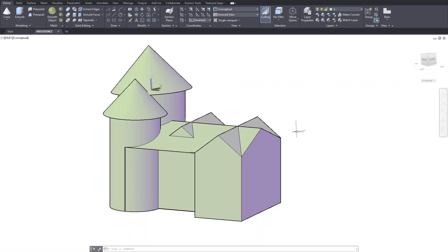And then you need a land, obviously, okay? You have to have some kind of land at least, some kind of ground, and the windows. So we're gonna do this right now. So I'm going to just move our UCS again on the surface in the hope to create the door, okay? And I'm going to just simply type UCS, enter, okay? And it gives me a number of options here.